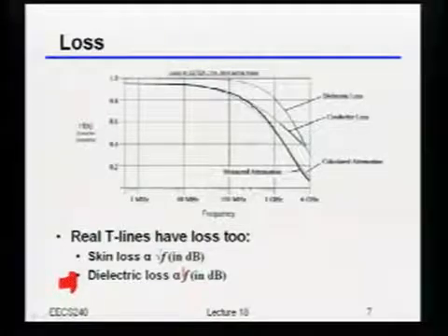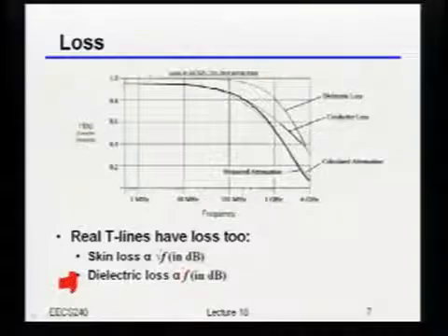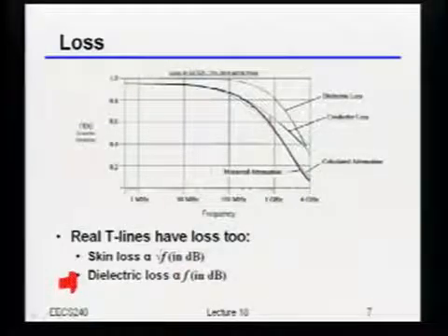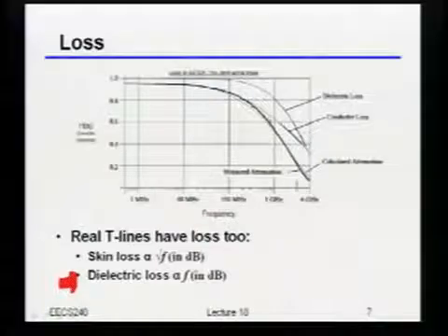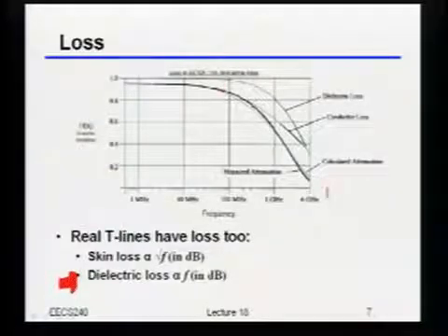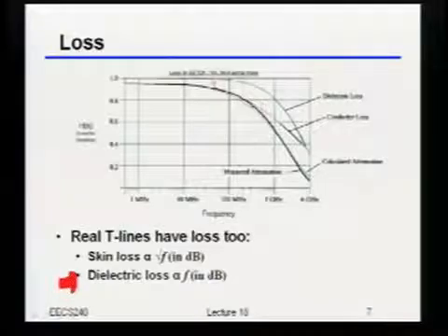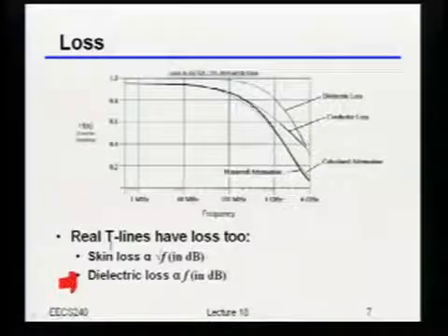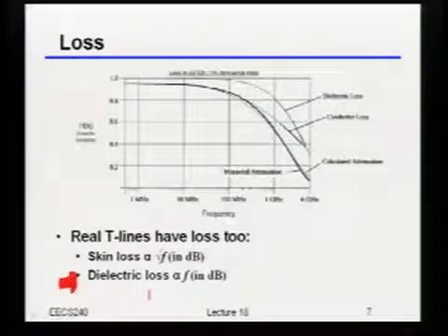If you look at the transfer function of one of these transmission lines versus frequency, you'll usually see very, very low loss at low frequencies. As you go up to higher and higher frequency, first the conductor or skin loss comes into the picture. And then once you go to high enough frequency, you're basically dominated by that dielectric loss. Okay? Now,